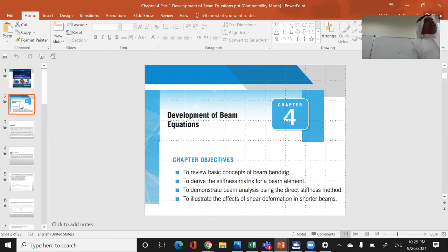Select element type. Because it's a beam, you will use long one, right? 1 dimension. You will not use the area and you will not use volume, right? Just like the rod. Okay, so this is the type. Then what? What is step number 2? Discretize? No.